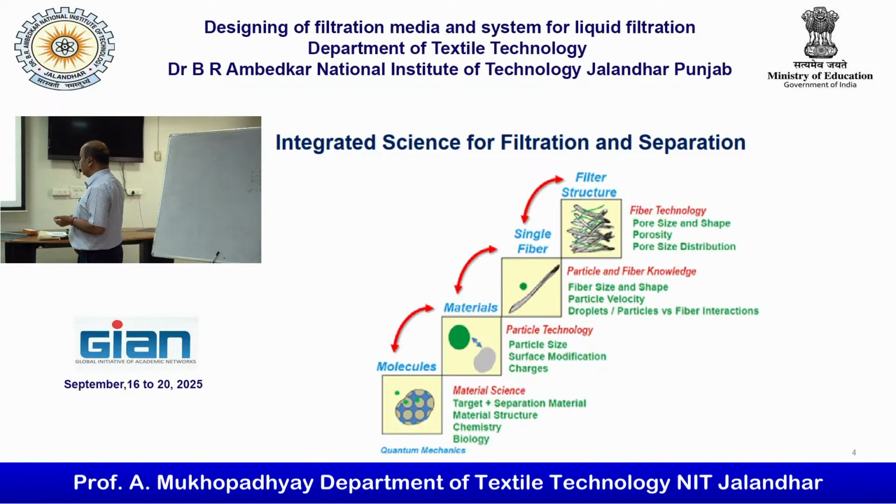So material consideration is also very important. Then particle and fiber technology: fiber knowledge, fiber size, shape, particle velocity, droplets, particle versus fiber interaction. Single fiber theory is important, but as I told, in liquid filtration it is not much applicable, because the role of fiber assembly is very important.